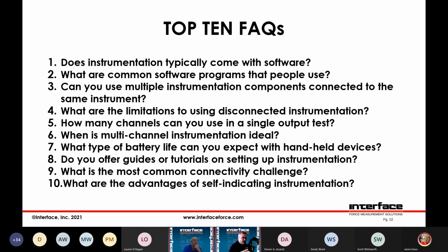Just because you have a low level millivolt input, it doesn't mean that a load cell hooks up to it easily. And so what you probably want to do is use a signal conditioner and actually use like a 5-volt input range, and use a signal conditioner to bring your voltage up to the higher level input.